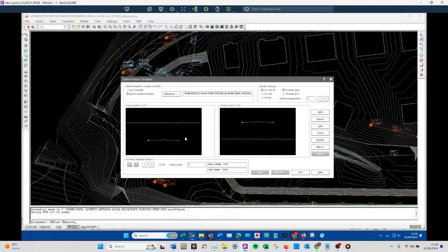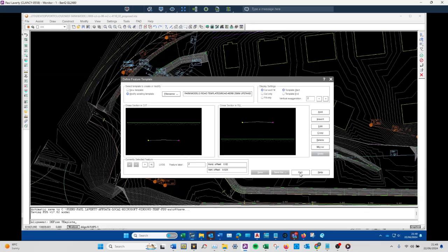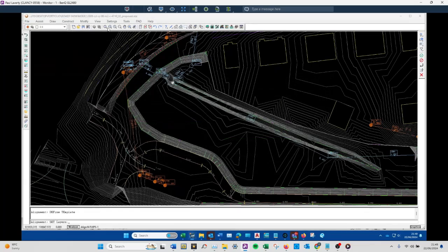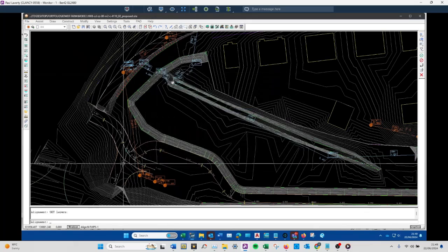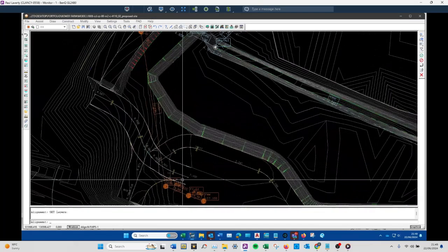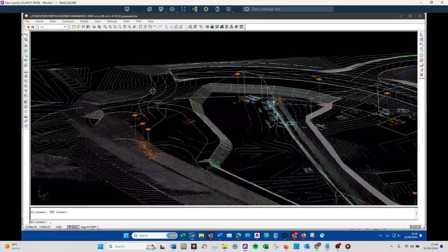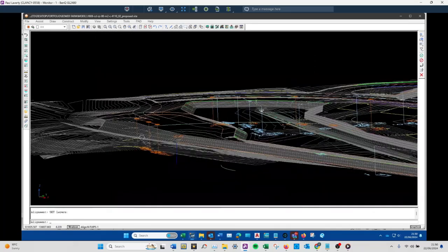And then you say, great, let's add a footpath. So let's add a 2 meter wide, 1 to 40 footpath all the way along there. You go back into your templates, you choose your 2 meter footpath, you drop it onto it, great, happy days. Then you want to do a swale, go into this, and if you've got one already created, you can just drop it right onto it. Now I've got mine for the more typical ones. So it's really easy when you bring your template folder in, because this will be set up.